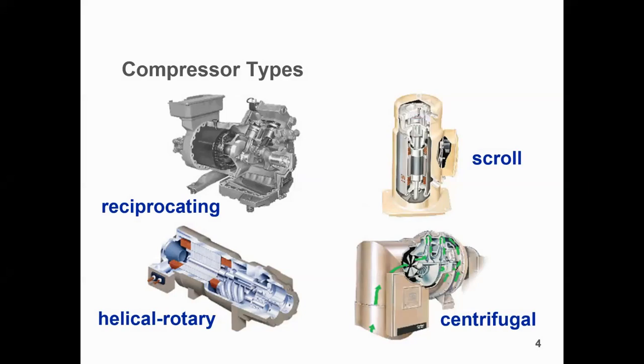Now getting into the different types of compressor which are available. These are the basic compressor technologies which are very common in our industry. One is the reciprocating compressor. Nowadays we have stopped using it because it has become outdated. Earlier we used to use it, but now that entire place has been taken by scroll compressors and helical rotary compressors, which are also famously known as screw compressors. The scroll compressor we normally use for smaller applications. Mid-size applications are catered to by the screw compressor, which is helical rotary. And once you get into bigger applications, that is bigger capacity chillers, obviously we have to switch over to the centrifugal compressor.